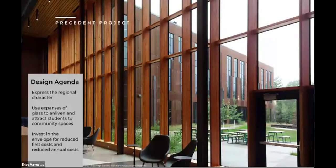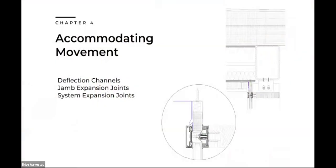So one more aspect on these control layers is also accommodating movement. We talked about in the structural portion how we need to account for deflection of the system, and just wanted to show you a quick detail of a head condition where the deflection may be more than what you could accommodate with a simple sealant joint.